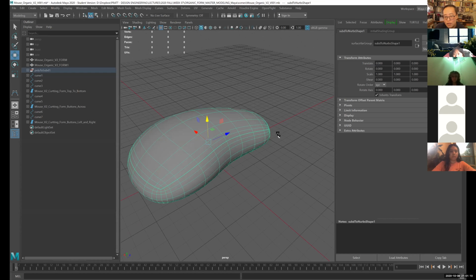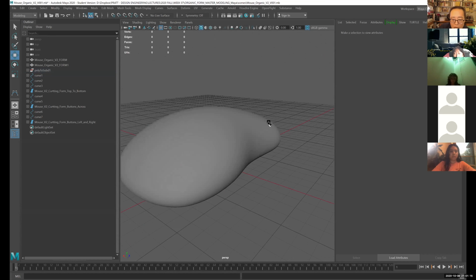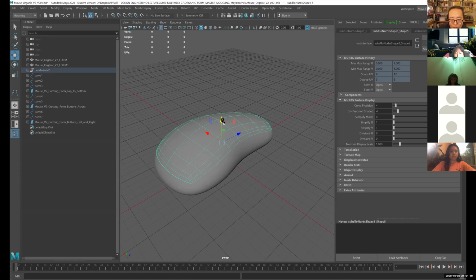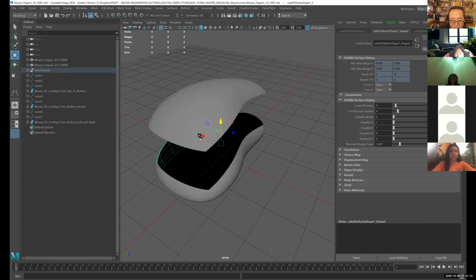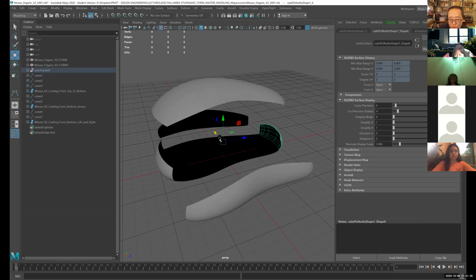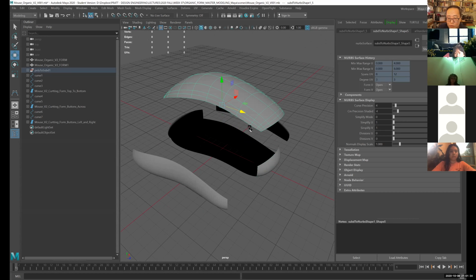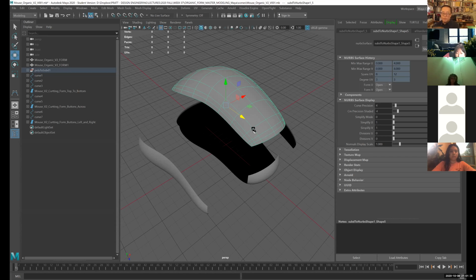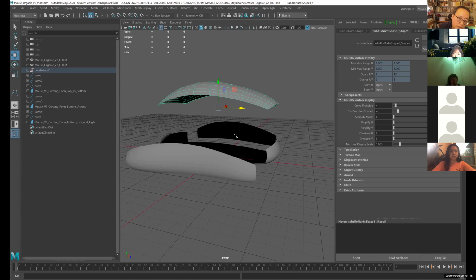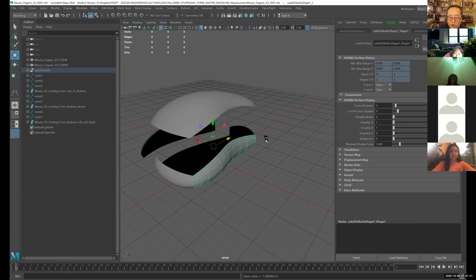The form and the shape is the same, but this is the difference. Watch. If you pick a surface here and move it, it gets taken apart, right? Can I have just one thing and not taken apart? Well, not really, because Nurbs geometry math works on the principle of four-sided patches. It's the U direction, like the grid, and the V direction. It's a two-axes, base kind of math. So Nurbs geometry has to be describable by a series of four-sided patches.